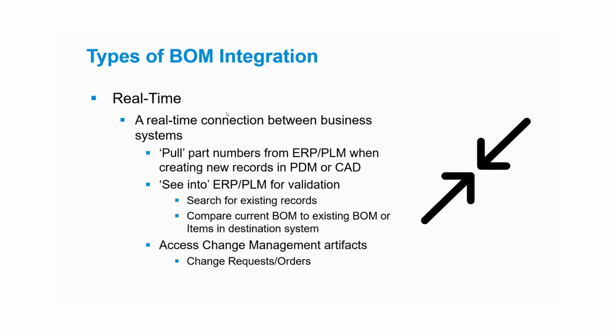If all you're looking to do is get part numbers, then there are other methods to do that. It could be a simple add-in for Vault or Inventor. Vault Professional technically now has the ability to use a third-party source to give you part numbers. It's not trivial to implement, but it would be a lot easier than implementing an entire PowerGate implementation just to get part numbers, which is probably overkill.